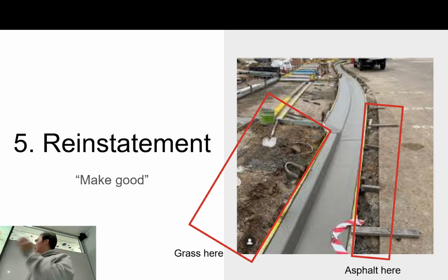So I'll reiterate again the reason that we did that. We want the concrete to have a nice smooth finish, right? So we want to make sure that the edges are super nice. So that's why we cut out the concrete, the asphalt in the road. We need to replace the road base, and then we need to pour the asphalt again for that. But usually that can be done maybe a week after. Actually, no, a couple days after, and that's fine.